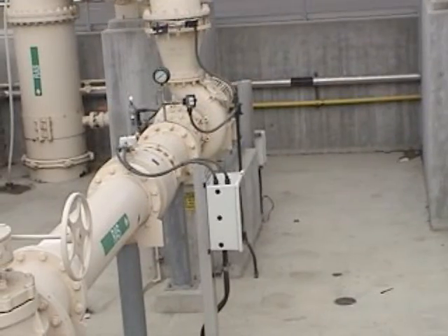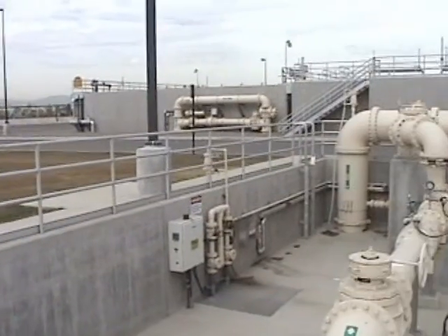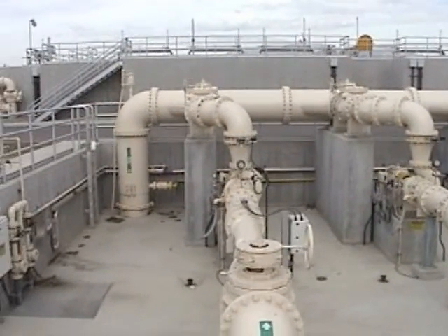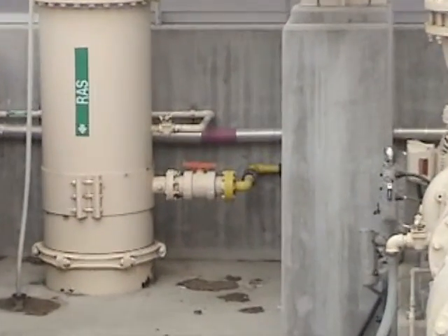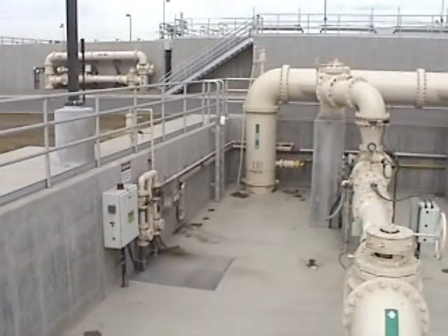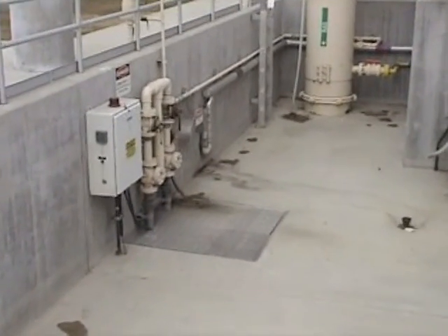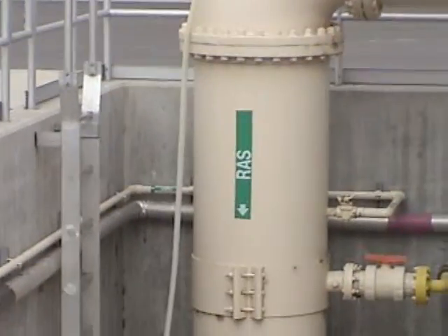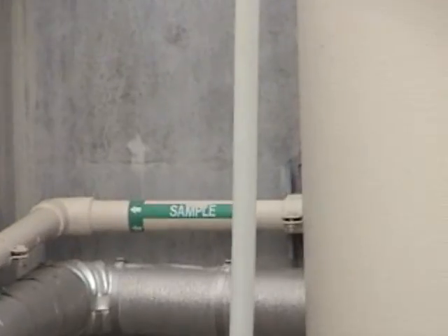If we ever have to chlorinate the secondary system, that piping right there, the yellow piping running along the wall back there and feeding into the RAS pump, is where that chemical is introduced to the secondary system. To collect a RAS sample, it's done right there by that sump. You can see that pipe down below there. That sample is pulled from that main RAS line with the arrow pointing at the floor. If you see just above the yellow pipe, that other brown tan pipe attached to the wall right there, that's where the sample is pulled from.